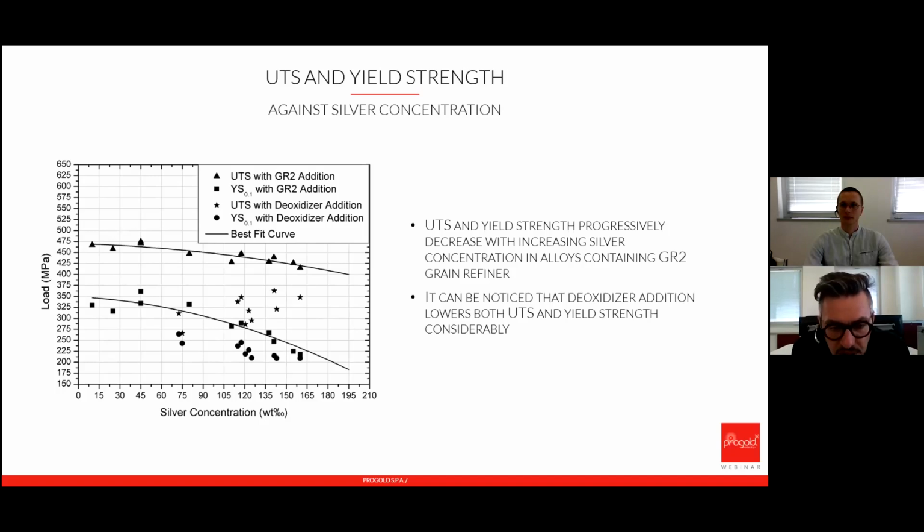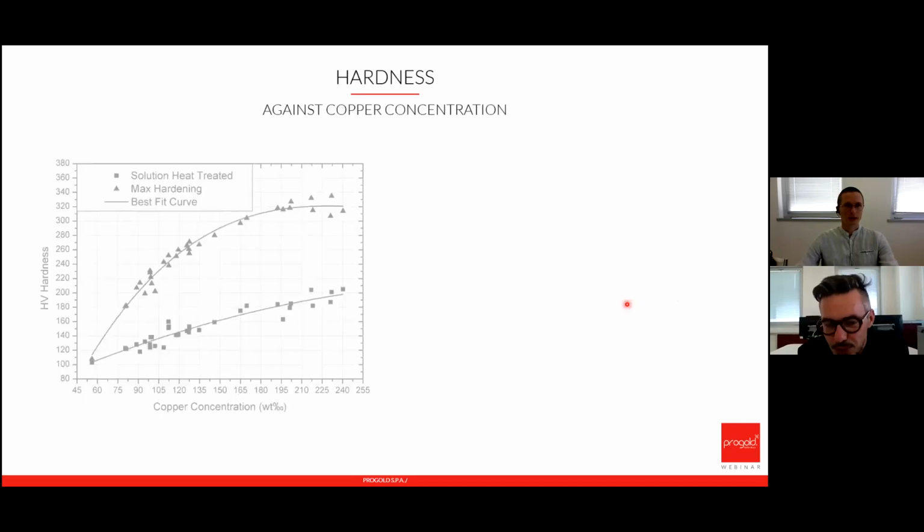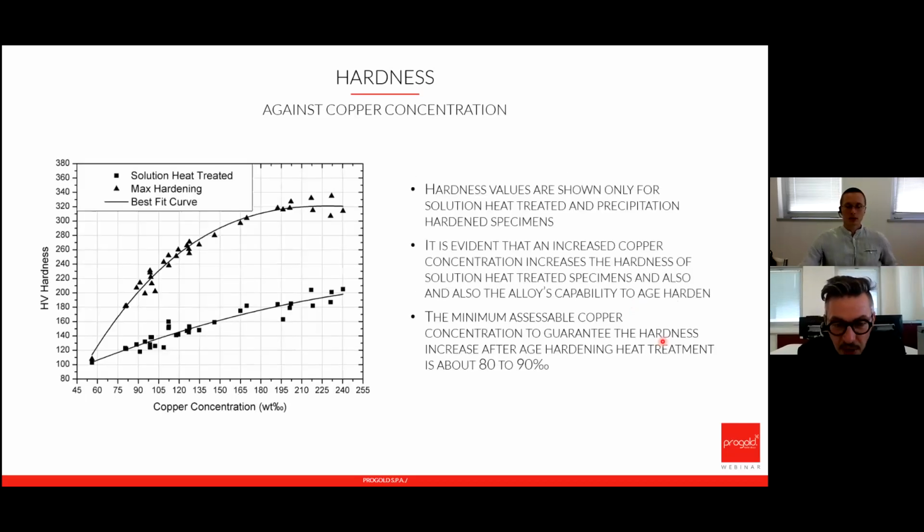Without generally mentioning the concentration, so I don't know. Let's try to tell something about the meaning in terms of hardness in 18K if you put more copper or less copper, balancing with the silver, so red and yellow. Hoping that we are able to answer in this way, because the question is not well clear. Only talking about 18 karat alloy, the most important, as we said, is the copper content, because it's the only one that has a hardening effect on the alloy.